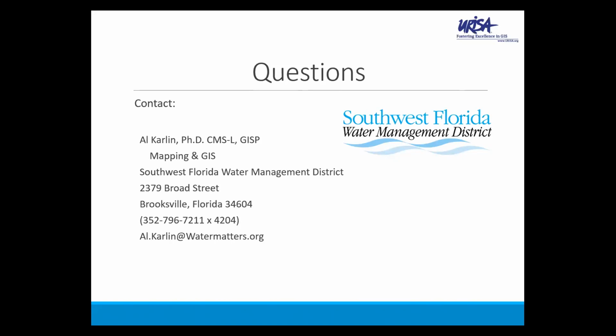The geospatial definition of a datum is simply a reference surface or plane. And it's the surface to which we reference coordinates, whether they're XY coordinates, horizontal coordinates, or vertical coordinates. So in the case of GPS collected coordinates, those coordinates are referenced to the ellipsoid, a reference, in this case, it's a reference sphere.